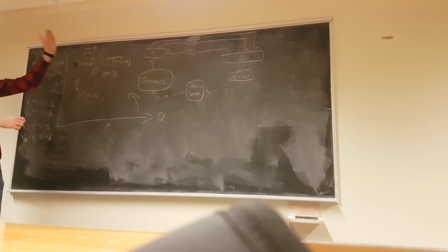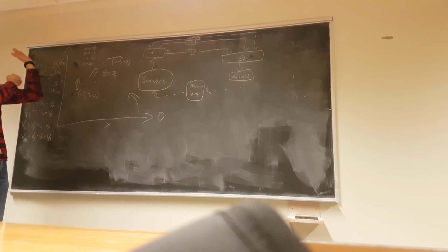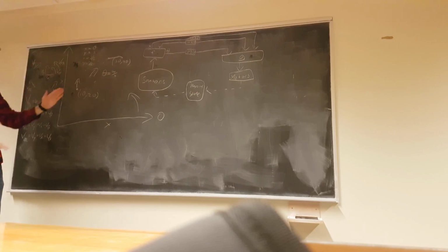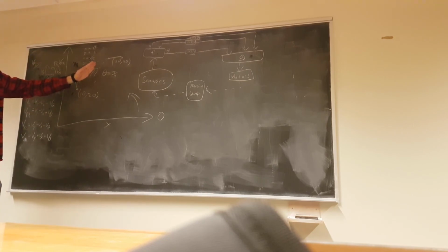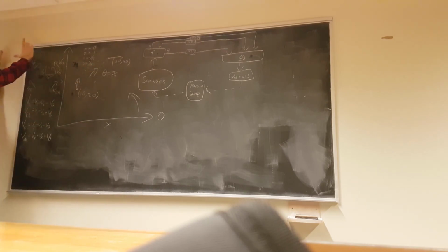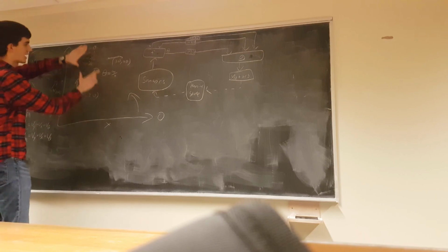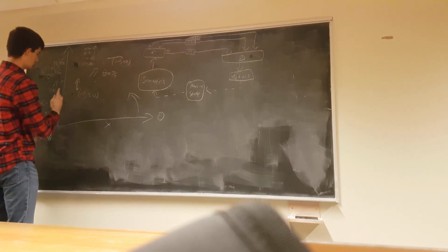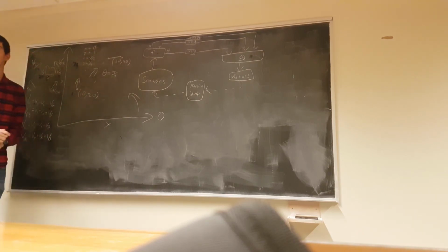That means taking this vector and rotating it that way by 45 degrees. You get something that's negative on x, positive on y. The robot's here, and it moves negative on x, positive on y, equal amounts, relative to the robot, it's moving that way, right? If it's moving that way, it's moving in the direction we want, which is the positive y-axis.